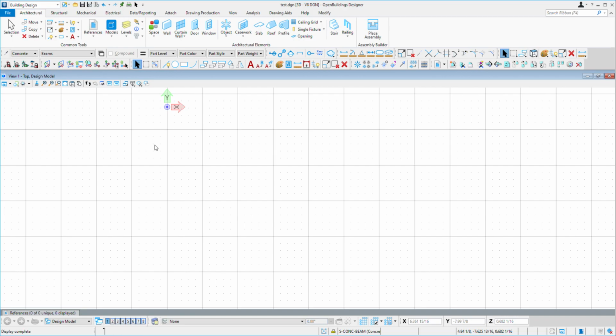Tags: some of the cells have tags, like attributes as we call them in AutoCAD. So it is for dynamic blocks and dynamic cells. If we have some tags and you turn off this tag option, all the tags are turned off. Same for text notes, and transparency is also for drawing production, and it is only for viewing.